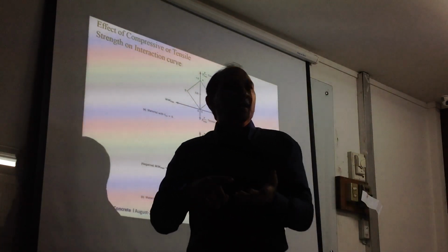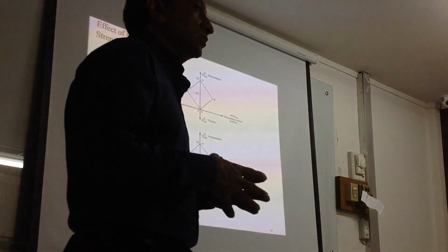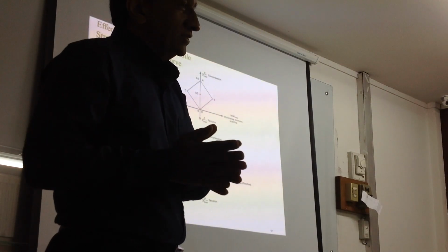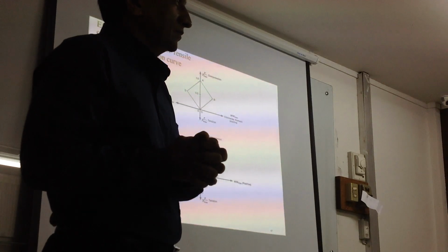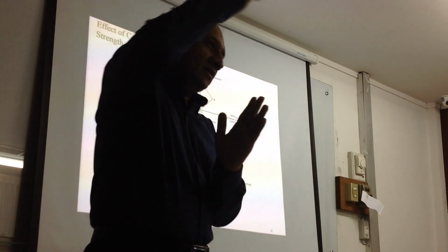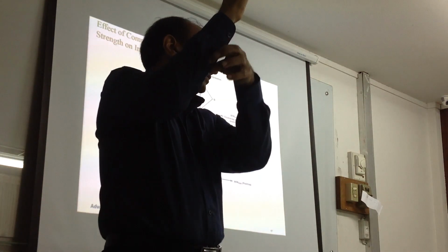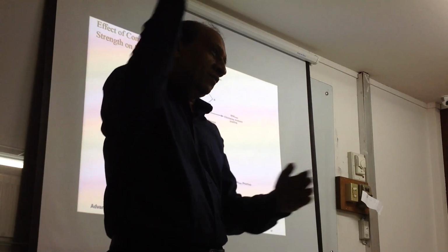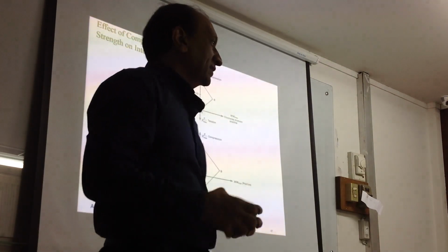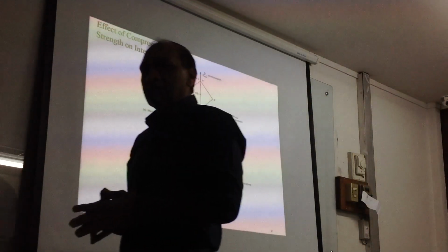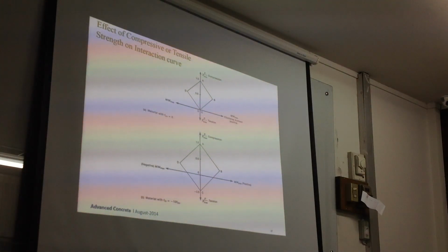It can happen easily, and this is very interesting because many engineers do not realize something which you will learn in the next course, but I'll just tell you, stage construction causes tension in columns. Also, an extreme earthquake causes tension in columns because when you bend the building too much, these columns will become in tension. Or with too much wind, if the building is not big enough, the columns can become in tension. And stage construction loading can also create temporary tension in the columns. But I don't want to go into detail because then we will skip the topic. We will learn about that next time.